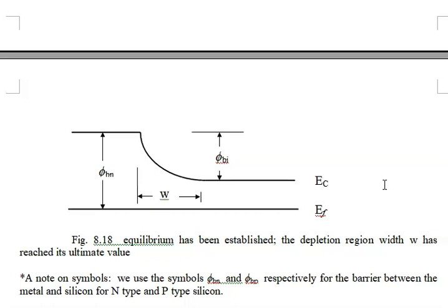It's N-up. And nup is not a very good thing. N-U-P, I don't know. It's not catchy. You know, like D over mu is KT over Q, it rhymes. I can't think of a nice way to remember that. But the bands in N-silicon will always bend up at the depletion region.